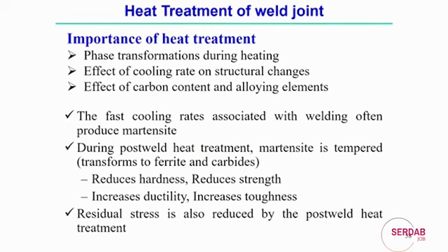The heat treatment modifies the microstructure, and that microstructure impacts the weld joint strength as well as ductility. Heat treatment is often associated with post weld treatment to obtain a good weld joint, or to recover some amount of the ductility of the welded joint.